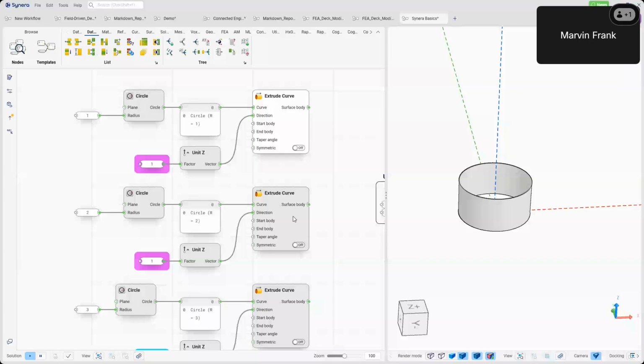See that this is exactly the same here. So we just copy this here all over, and instead of using everything here 2 times, I use a list here, and I created the list using this merge node. So merging has nothing to do with merging geometries or meshes. This is pure data structure. I have one data item here, one data item here. So that's my 1, that's my 2. And then you can check out the data structure here with the panel.